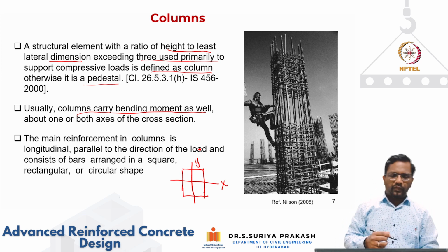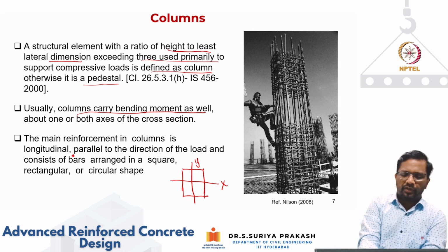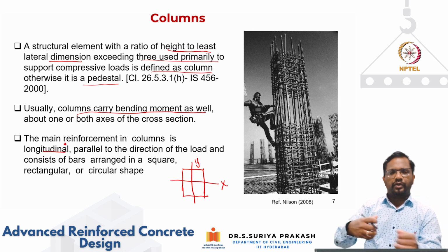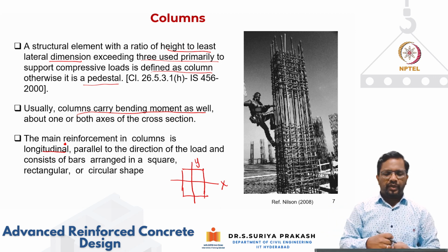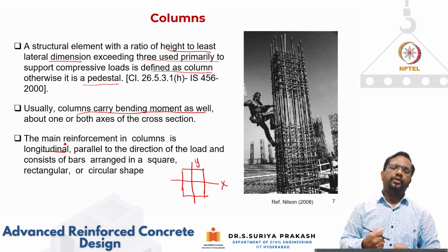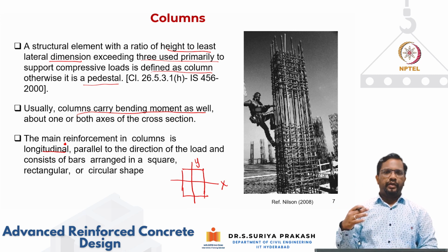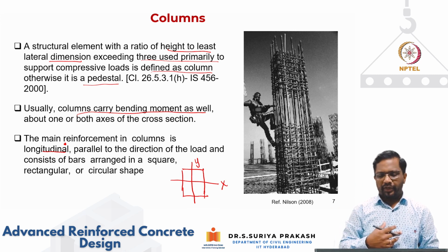Usually in bending, the main reinforcement in columns is longitudinal, because bending creates normal stress. So the longitudinal reinforcement is going to carry the tension coming from your bending.